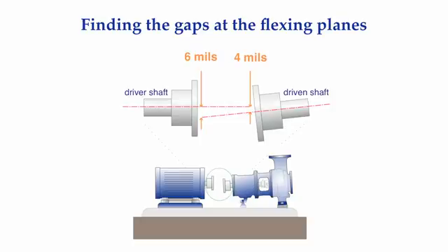An alignment model is an exaggerated picture of the misalignment condition of a drive system. Not only can the positions of the misaligned shafts be shown, but additional layers of information can be superimposed on the alignment model to show offline to running machinery movement, boundary conditions, and external connection problems, along with how you can correct the misalignment condition. But that's getting way ahead of where we are currently at.